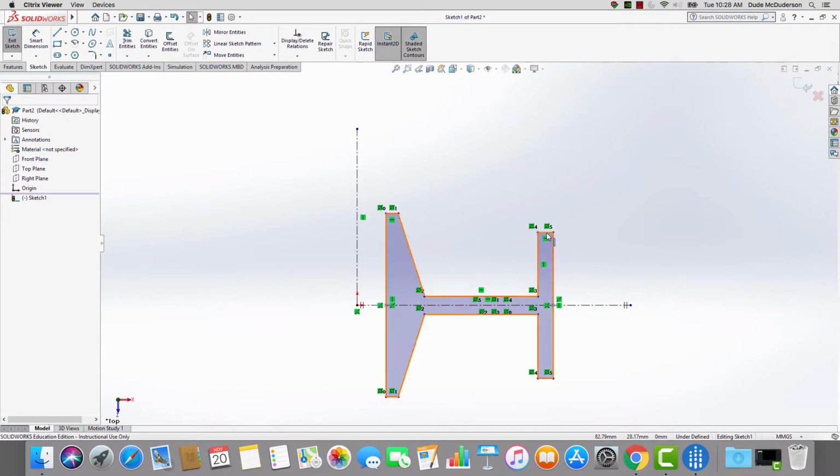You'll see now we have a ton of these relationships that exist throughout the drawing. The most important ones probably are your verticals and horizontals. This coincident relationship of that line starting there and the coincident relationship of the line finishing there. All of these numbered values here are indicating a mirrored relationship. So this number 4 here goes with this number 4 here. The 2 and the 2 of those points there, the 1 and the 1. So you can kind of follow the logic here of how SolidWorks thinks about this as you go. So with this in mind, now I can go ahead and start the dimensioning process, which is going to fine-tune this geometry to be exactly what I want it to be.